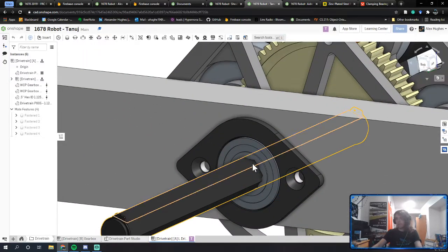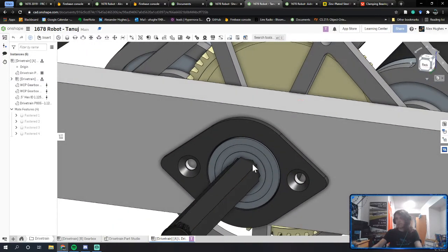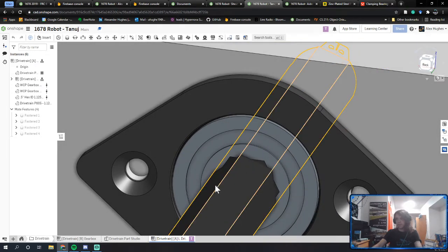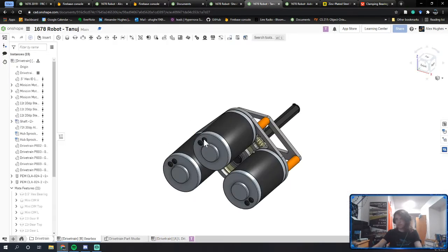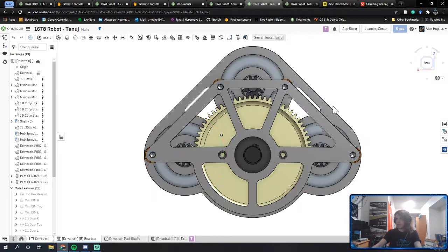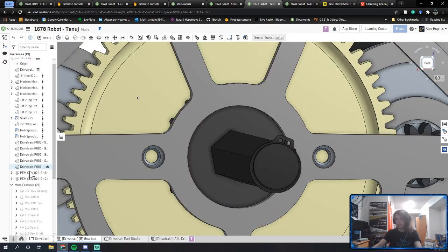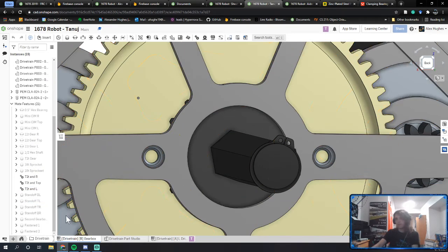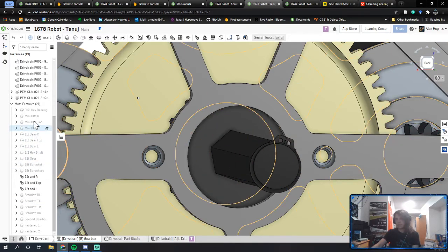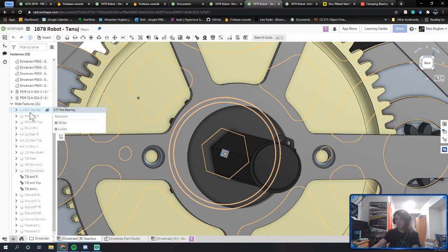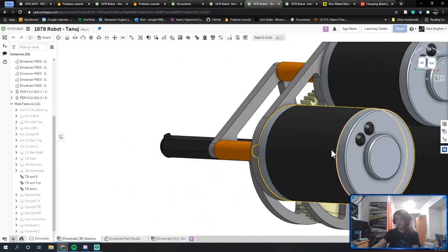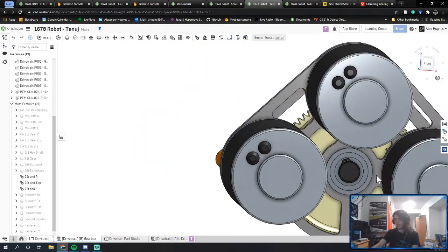For the most part, you can ignore these. It's just kind of an OCD thing that I have. So you might want to actually go in here and look at your regular gearbox. You can notice your hex shaft is actually rotated in the gearbox itself. You'd want to find where that mate is, and possibly change that.